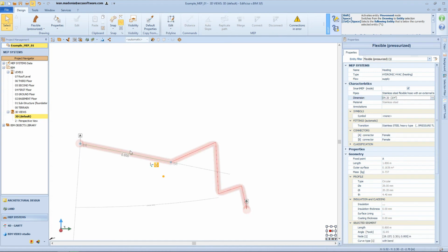Furthermore, by clicking on one of the connections, a broken line appears that joins the ends of the sections that make up the hose, if there are more than one, otherwise it leads back to a single line. The segment relating to the selected segment is highlighted in green and all the others, if present, in red. Relative to the selected section, the extremes are specified with the numbers 1 and 2, and highlighted with gray circles. The length of the selected segment is also shown in gray.